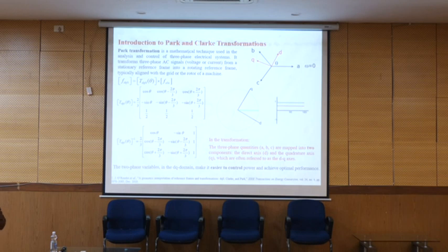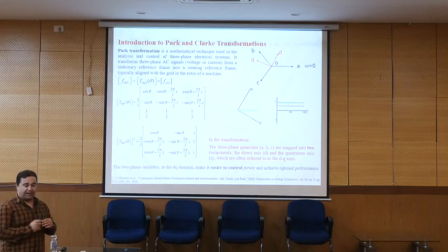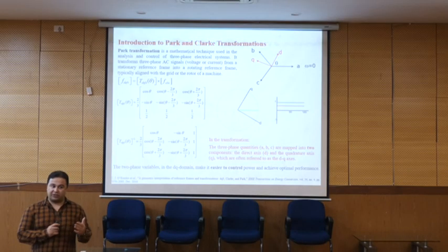When we think about 2070, it doesn't mean that we might not reach the point probably in 2035 where renewable energy creates more problems for us. It's possible. We started to integrate renewable energy in the beginning of 2000. Then when we reached 2009, 10, we noticed that when we increase the level of renewable energy, we have instability in the frequency of the system. And then they noticed that this is due to the lack of inertia.